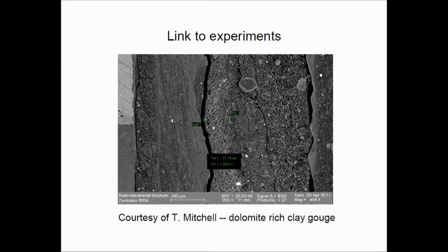This is a specimen, and the cracks, at least we were told by the person who did it, Tom Mitchell of Liverpool, came later when the thing was taken out of the apparatus. But you can see these white markings, which are evidence of extreme decomposition. And you can see that this stuff here shows signs of strain, but it's less decomposed. So this may be an example of a migrating thermal decomposition zone.